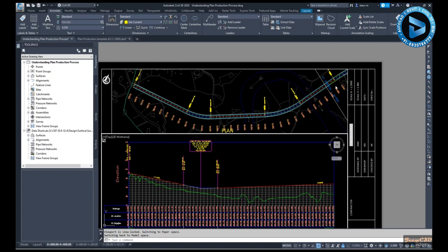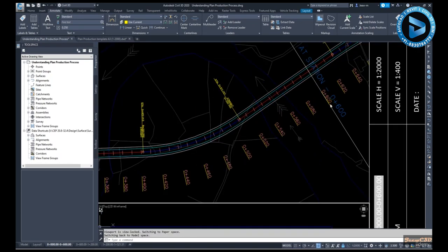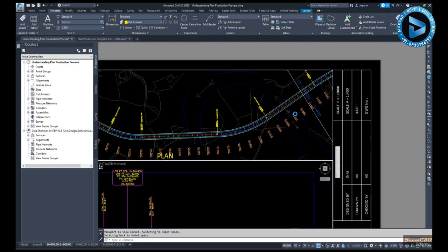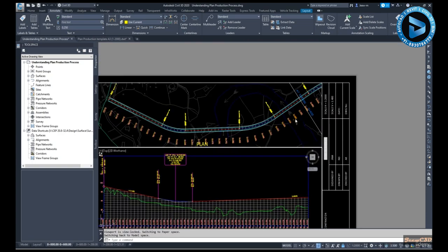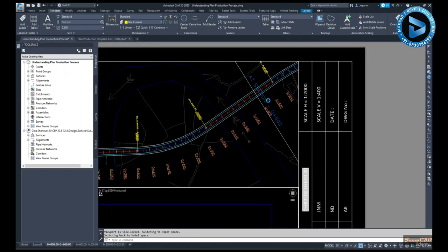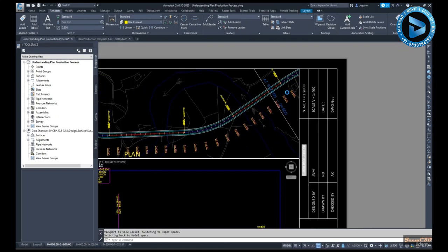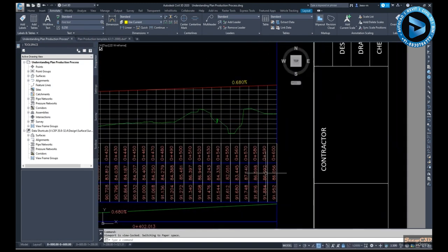After the match line, that part relates to the other sheets. Up to this match line, we have this drawing. We have data in this drawing because we don't have profile data after 600. Even though we check the plan beyond 600, we don't have values in the profile.